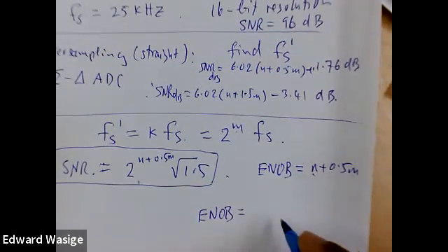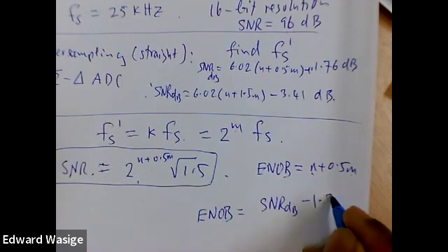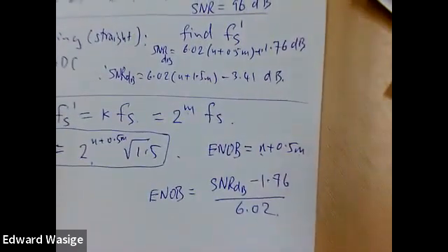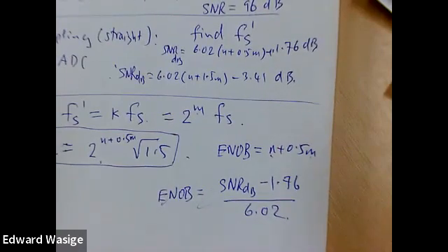This is equal to SNR in decibels minus 1.76 divided by 6.02. I'm probably just overdoing this a little bit, and I probably don't need to carry on here.